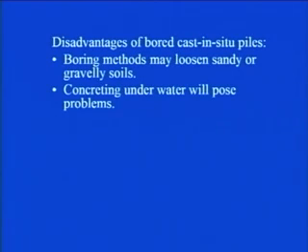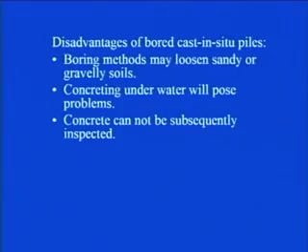Concreting underwater will pose problem because it is cast in situ. You are creating a void and then you are filling that with concrete. So, in case the water is present somewhere along the length of the pile, that can pose the problem. Then concrete cannot be subsequently inspected.